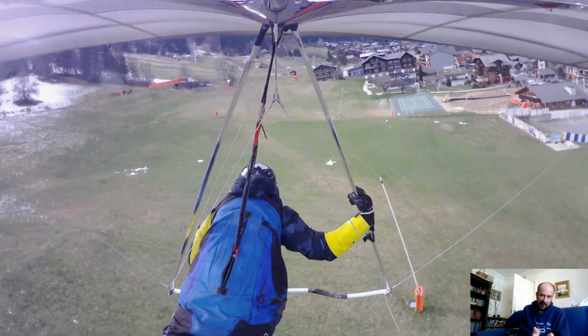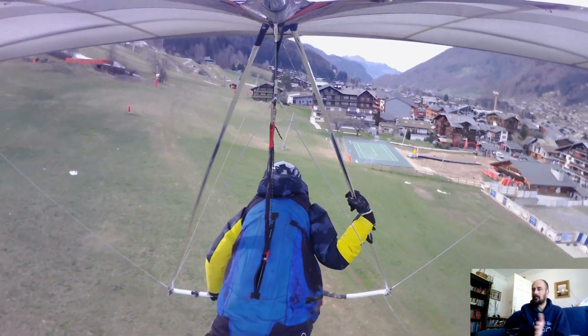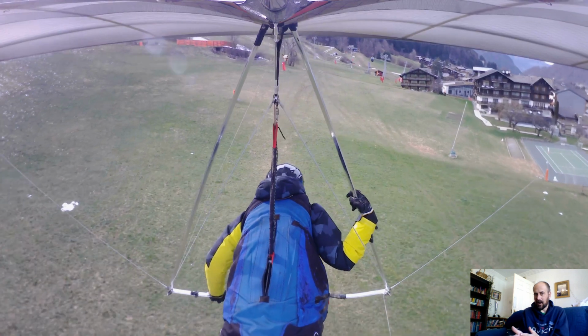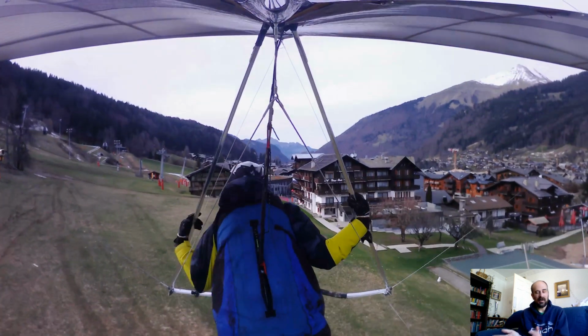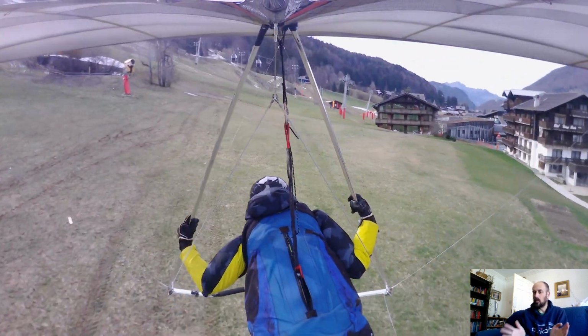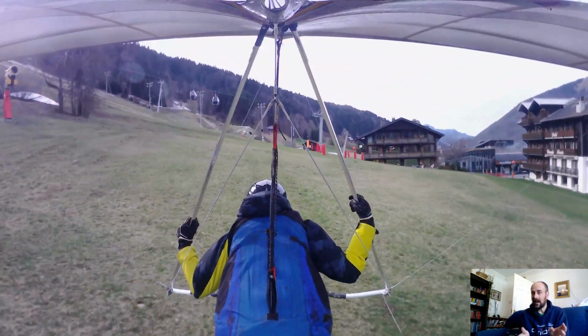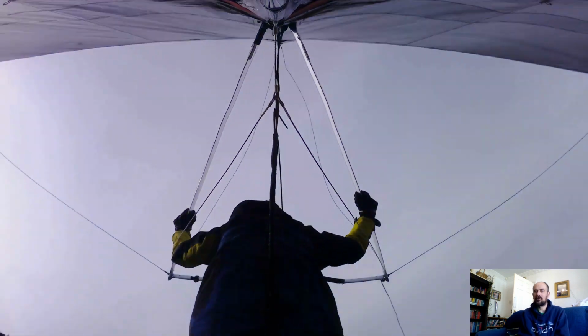That can also mean that it's more efficient at low speeds as well, so it reduces the stall speed, which then means if you've got a lower stall speed, it's easier to land. Potentially you can trade that for a slightly smaller wing area. If you have a slightly smaller wing area, you have less parasitic drag too. So now's a good time to talk in a little bit more detail about what causes induced drag.